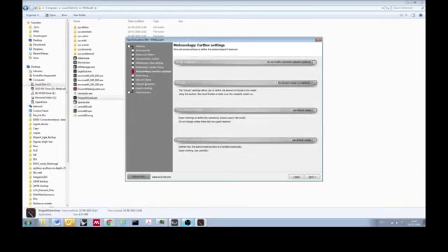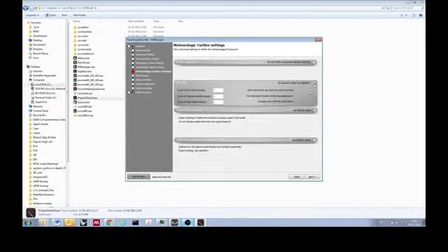In these next steps, we will not edit any of these basic settings, but I will just go through them. In the solar radiation, we can adjust the amount of solar radiation at the site, assuming, for example, that we have a really polluted area where our radiation cannot get up to the measured levels in other situations. We can modify this as a lower fraction, and also we can adjust the clouds. This is another way to do it.